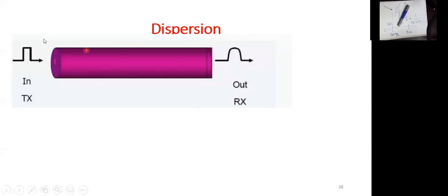That's why whenever you have these sharp edges, which are the indication of high frequency components, and you transmit your signal over an optical fiber, you have a smoothed output. This is due to the low pass filter effect. If you remember, we said that the optical fiber is a low pass filter system.